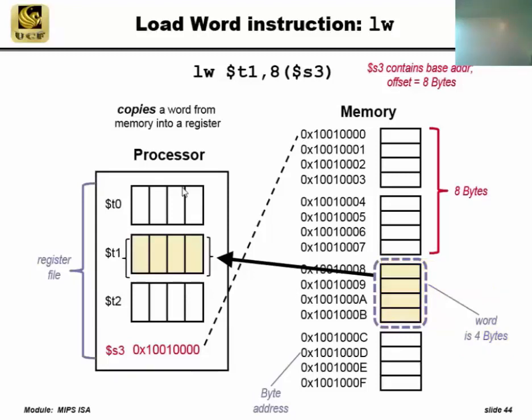Especially when you go to embedded systems, you go back even to 8 bits, because you have to put probes on each one of these bus wires to look at the data bits and the address bits. Like I said, we start working with 8-bit, 16-bit, 32-bit in this case, then you expand your word width once that's debugged. So here we wanted to go 8 bytes forward from this address, 1001 zeros. So this is 1, 2, 3, 4, 5, 6, 7, 8, the starting address for the next 32 bits that are going to be transferred.